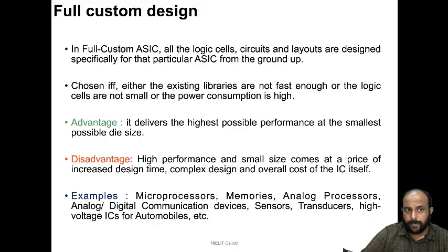First, let us look at what a full custom design is. In a full custom design, or full custom ASIC, all the logic cells, including the circuits, the layouts, etc., are designed specifically to target a particular technology node or a particular performance, and everything is built from scratch. This technology is very complicated, and it is chosen if and only if the existing libraries or macros are not enough to meet a particular power consumption.